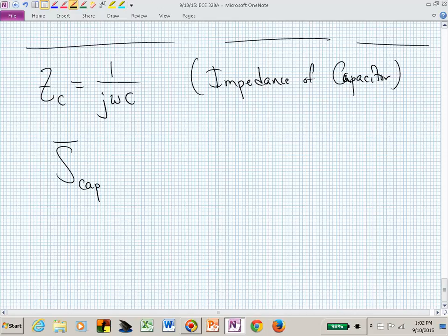But you now have the voltage of the capacitor times the current of that capacitor. Those two quantities are both phasors, and what else am I implicitly assuming? They're RMS units. A lot of times I don't even write that down, but I'm assuming that all of those phasors are already in RMS units.